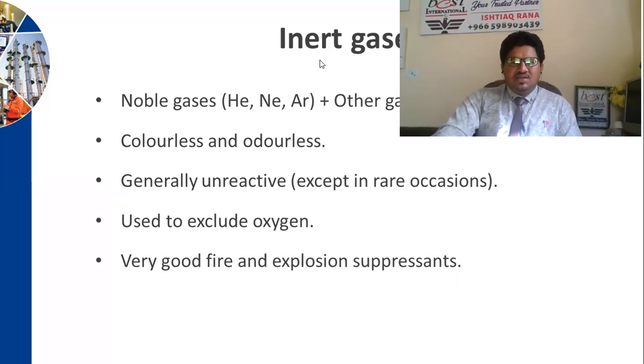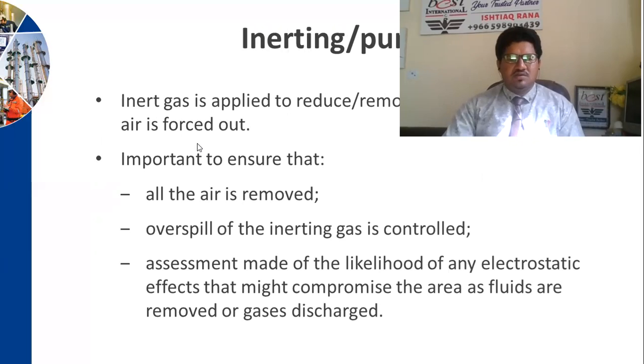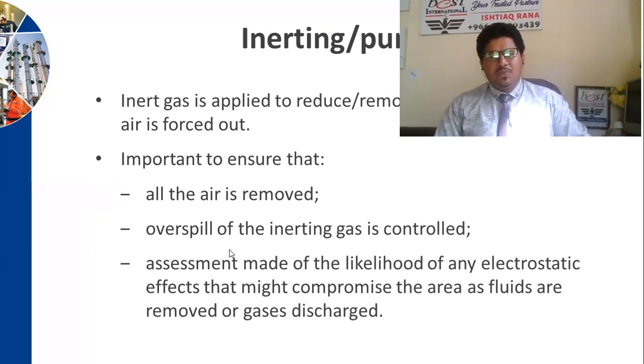Yes, you need to understand inert gases, like noble gases and other gases. They are colorless and odorless, generally unreactive except on rare occasions, used to exclude oxygen, and a very good fire and explosion suppressant. Also make sure you understand inerting and purging. Inert gas is applied to remove oxygen in the air. The air is forced out. It is important to ensure that all the air is removed.